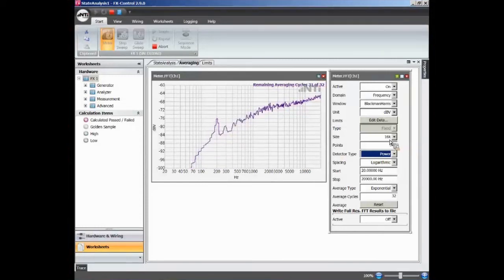You may notice here I have a 16K FFT, so that means the fundamental calculation includes 16,000 results, but I'm only displaying 500. It wouldn't make sense to display 16,000. You wouldn't get any more information. But by choosing this display mode, you get some more information about the distribution of the energy and the peak level that are happening in my input signal.